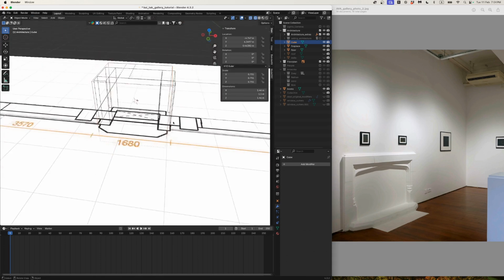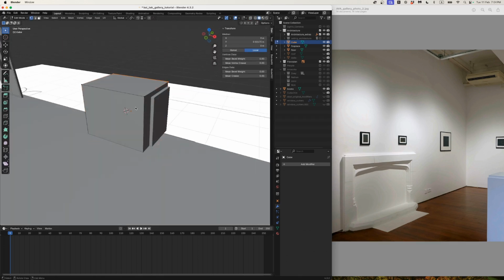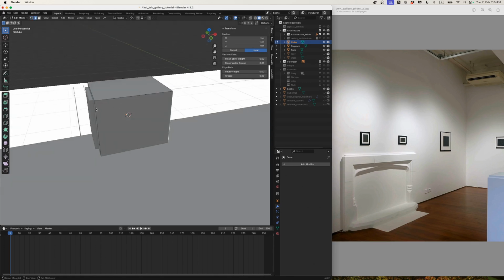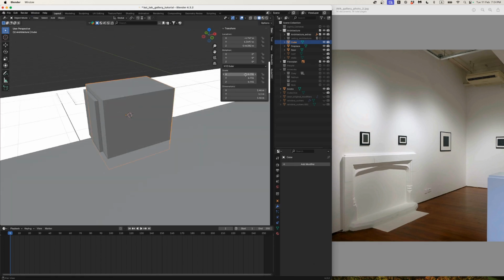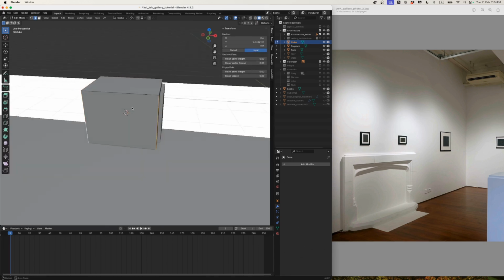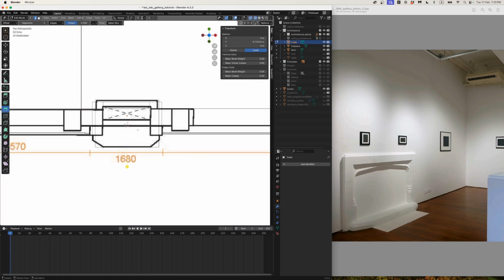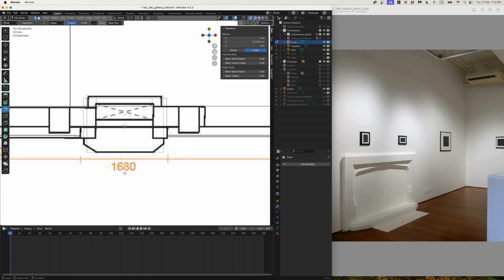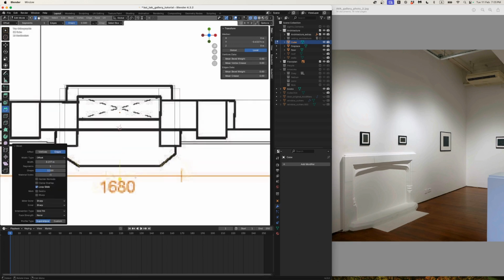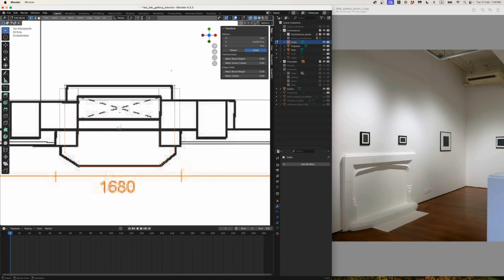Now I'm just going to do an operation called bevel here. So I go into edge select mode, select this edge and this edge. I'm just going to apply the scale first, apply scale, and choose my bevel tool. And bevel tool, if you click it, it does that. Okay, so I'm going to look from the top, go into wireframe. I'm going to see if I can bevel it to match. It's pretty close. And then I can turn off my bevel, and I can always just go into vertex select and just, you know, drag things to match.